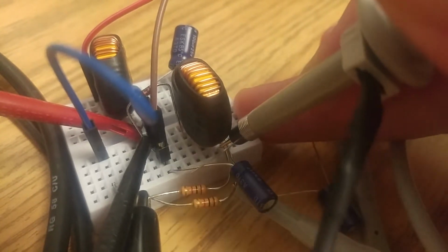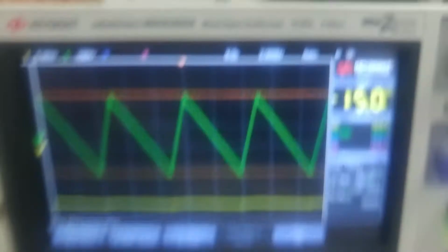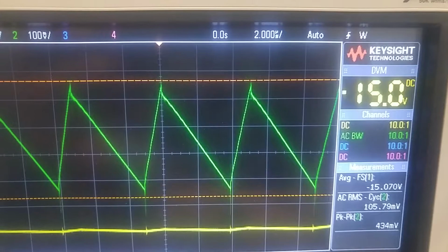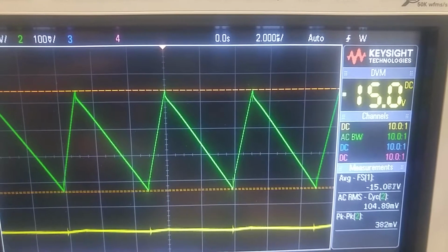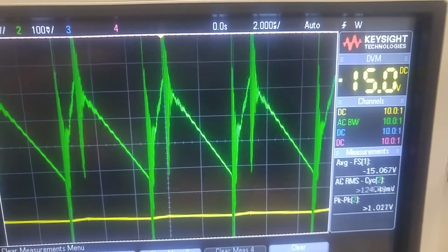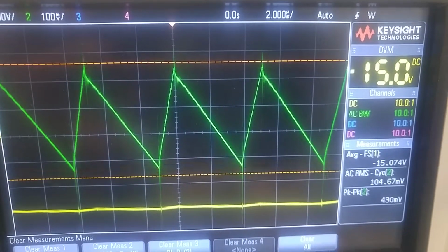Output node. This is my 0 node, and I have them kind of like sprung there, and it's a little shaky because it's a flaky connection. But when that connection is made really nice, those switching transients don't really make it any way through. It's a measurement thing and not a signal that was really in the converter.